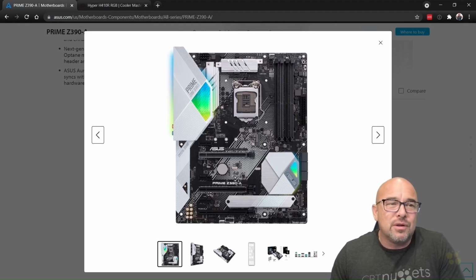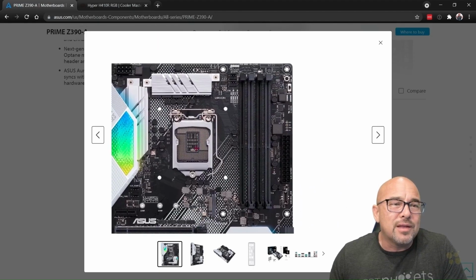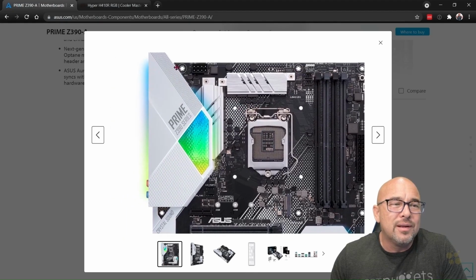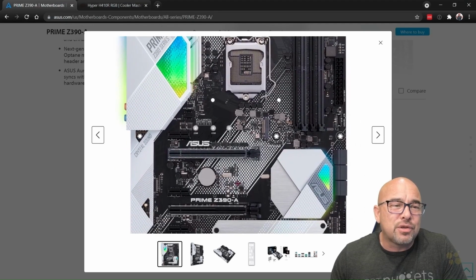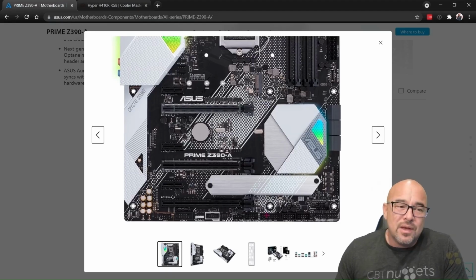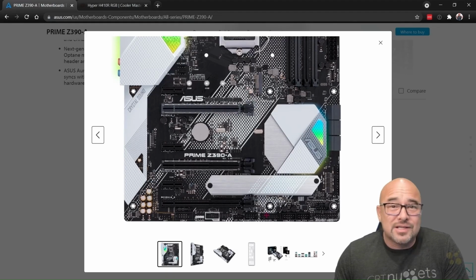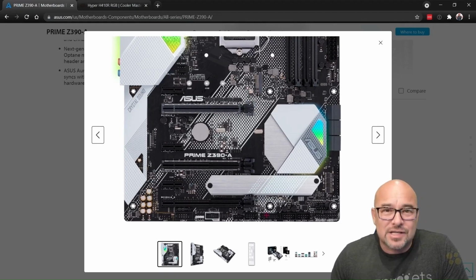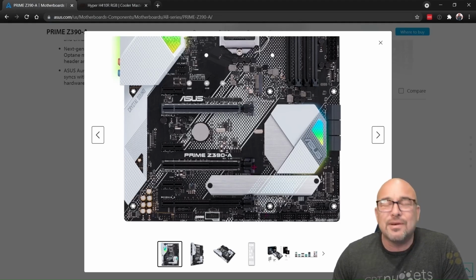If you look at this, there are screw holes here, and the screw holes are what attach it to the case. There's one there, there's one there, there's one over here. All of the things like the screw holes and the exact dimensions of this motherboard are exactly the same on any ATX-based motherboard. Different brand, doesn't matter. It's all going to have the same exact specifications. And that's just for the sake of standardization.